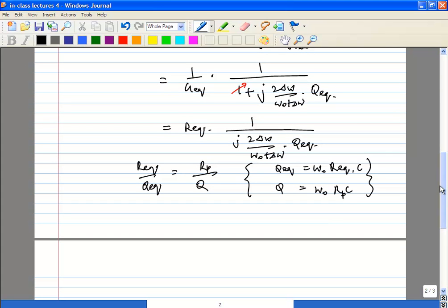Maybe I missed the usage of: you are making modulus of RA greater than RP, so L and C cannot cancel out each other completely. Why not? If they cancel out completely, then you will have a negative resistance part and the amplitude will become limited by the non-linearity.